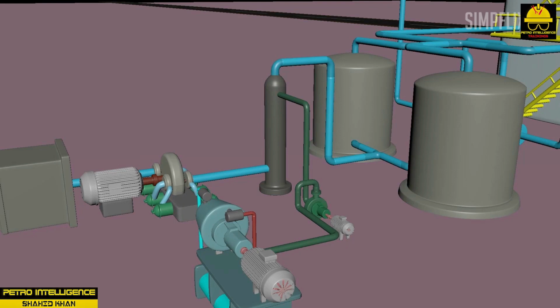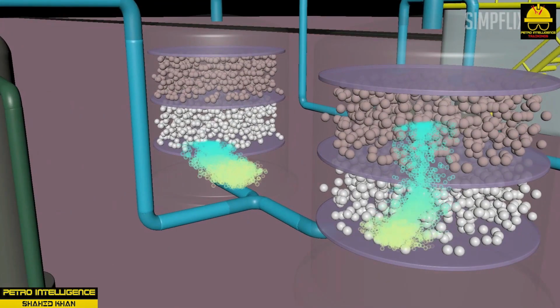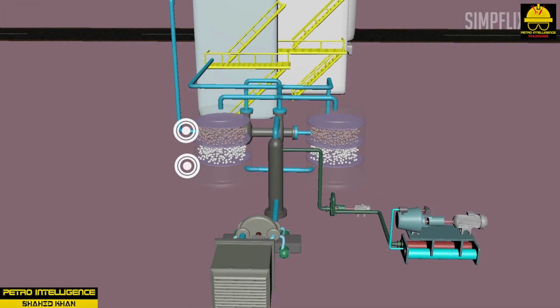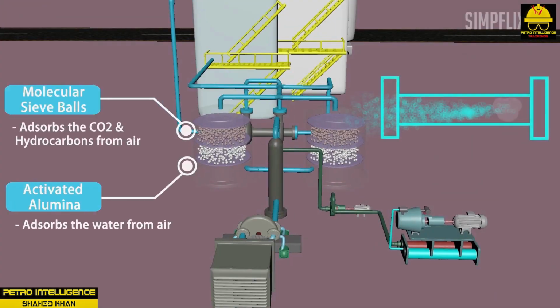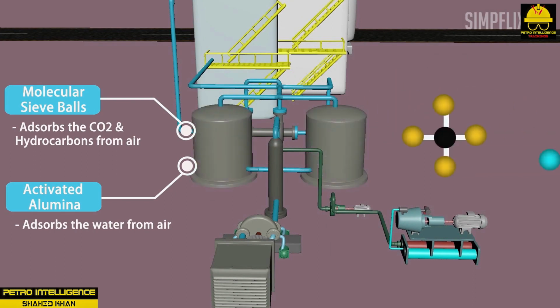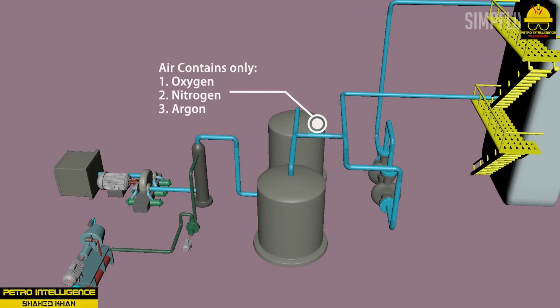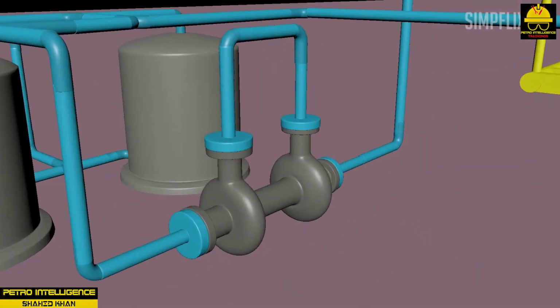During the oxygen cryogenic process, a compressor is used to draw outside air into the warm-in section and transfer it to a receiver. The compressed air generates heat and needs to be passed through a chiller before moving into the coalescing filter section. The final step takes the compressed air and sends it through an activated carbon adsorber. This completes the warm-in process.